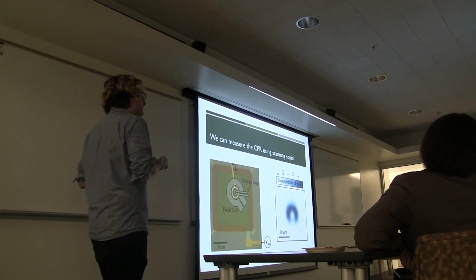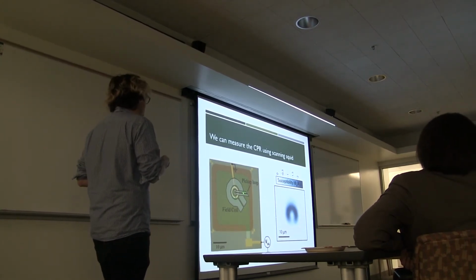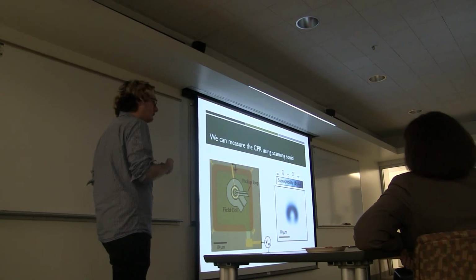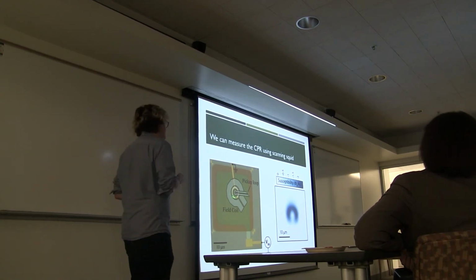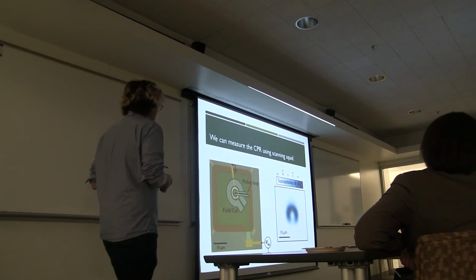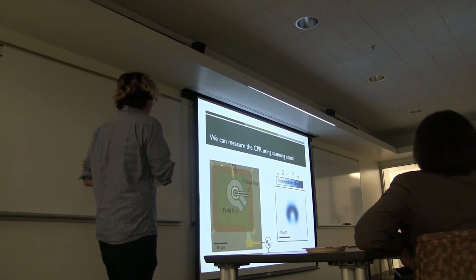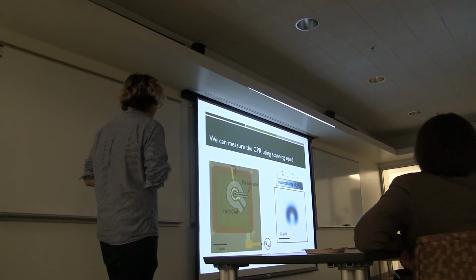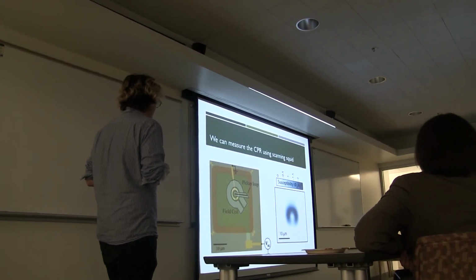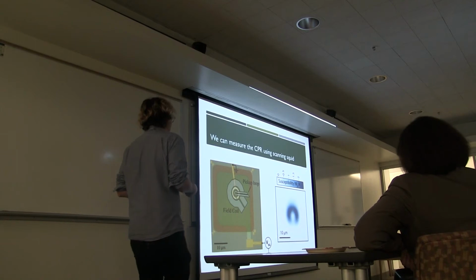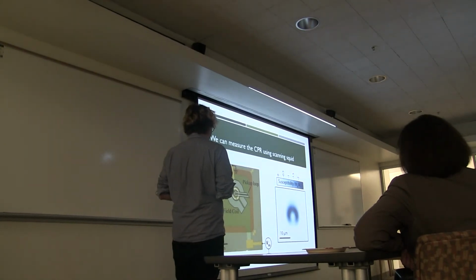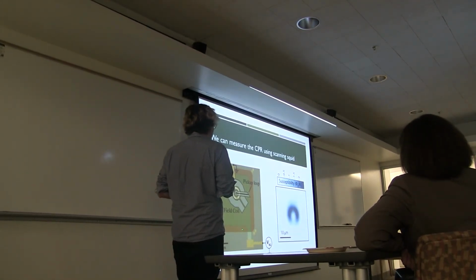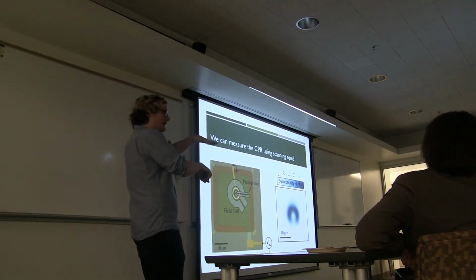Then the current phase relation of the junction will result in a circulating current around the ring, and we measure the signal from that current using our pickup loop. And so here's an optical image of our device. You can see that there's a loop here and there's a nanowire junction down here. The other feature of the most recent sample that I've measured is that it has a bottom gate. So there's a gold pad underneath with some dielectric, and then the nanowires on top of that.